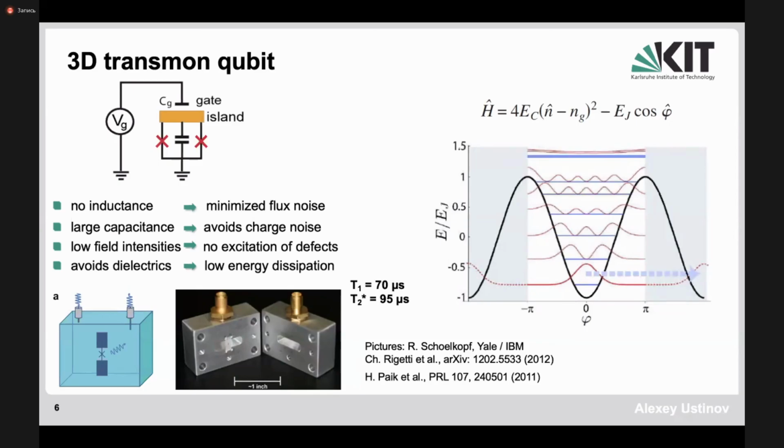And then here, in the geometry on the left, you see you have 2 lines. On one line you could send the signal in, on the other line you can send the signal out. Or you may eventually use the same line and then use 2 microwave tones. And what you do, you basically use one frequency, which you apply over one line as a readout tone. It will be close to the frequency of the cavity.